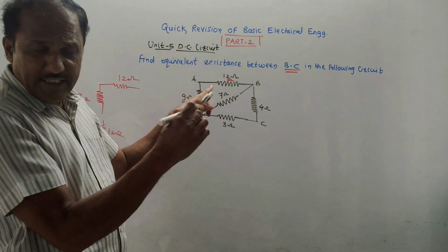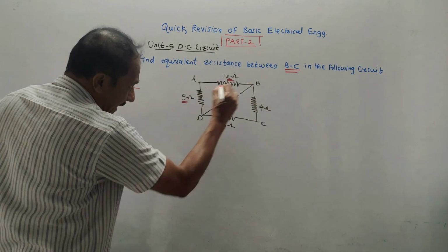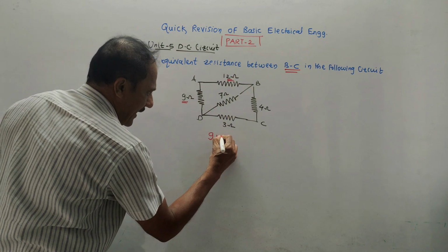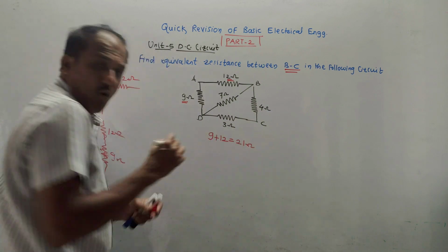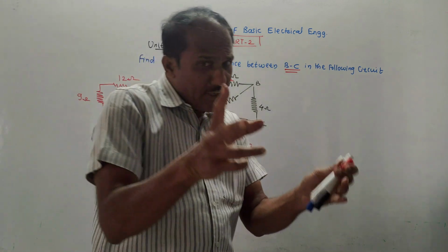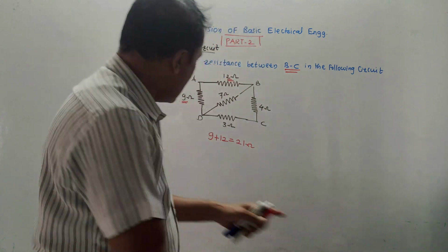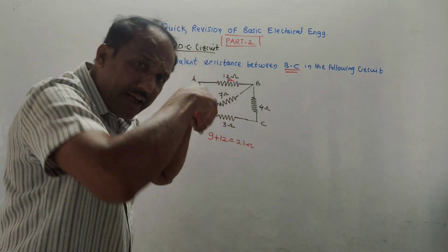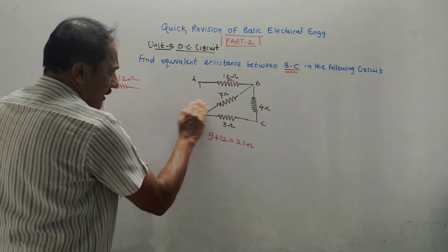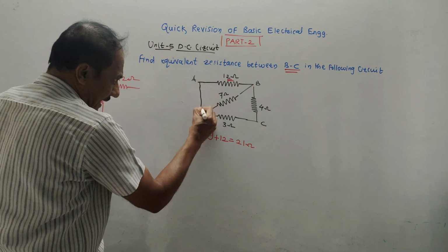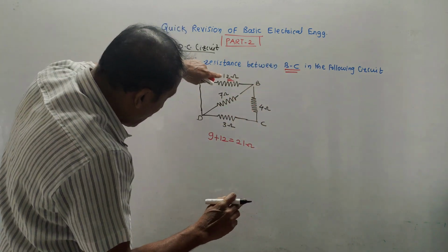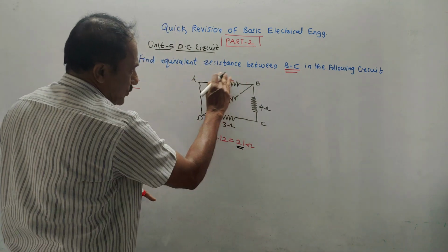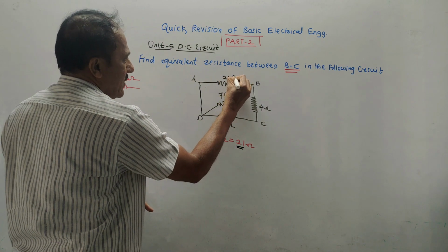When the resistors are in series, perform the addition. So in the exam, you can well write this as 9 and 12 ohms are in series. So combined will be 9 plus 12, that will be 21 ohm. Now another common thing. Whenever you take any series or parallel combination, remove any one of the resistors. For example, I will remove 9 ohm, keep another as it is. For the remaining, write down the resultant value which you got after calculation. So this value I will write as 21 ohm.